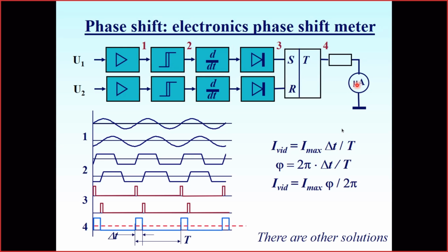It will not work if we have some digital device, a digital meter, because a digital meter uses the sample and hold approach. It's like it freezes the moment value and then transforms it. So it may freeze it at the 1 level of the output, and maybe freeze it at the 0 level of the output.